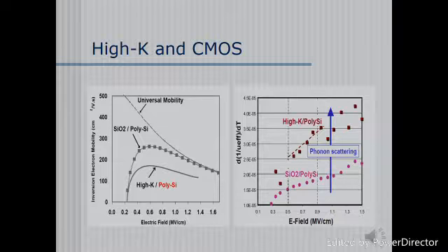It uses a silicon nanowire as the MOSFET channel, and has the metallic gate and dielectrics inside it wrapped by the wire. With atomic layer deposition and proper metal gate work functions, the MOSFET can be made. Unfortunately, this only solves the effective oxide thickness problem momentarily.